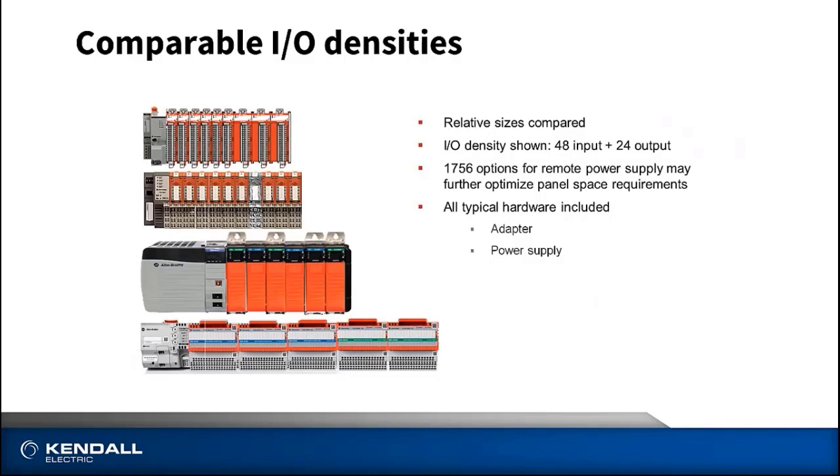And the third bullet there is also to make mention of the fact for the ControlLogix chassis, there is an optional cable that would allow you to detach the ControlLogix power supply and cable that power supply and connect it up remotely in case you have a situation where you just don't quite have enough horizontal real estate on your back panel. Maybe if you have room above or below the chassis, you can remotely mount that power supply and gain a little space there. In these examples, any hardware that's necessary to support that configuration in terms of the adapters or power supplies are also shown.